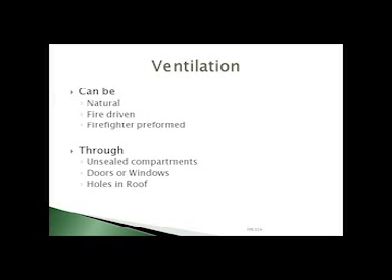Second is fire driven. As fire burns, it creates a pathway for the ventilation. It's very, very common to see fire driven ventilation in a structure that's nearly fully involved as the fire grows from one room to many rooms and starts hitting exterior walls or ceilings. It'll actually open areas in the building and ventilate itself. Not generally seen, from my experience, in a small fire, say one room and contents. But as fires get much larger, you'll start to see them ventilate themselves.